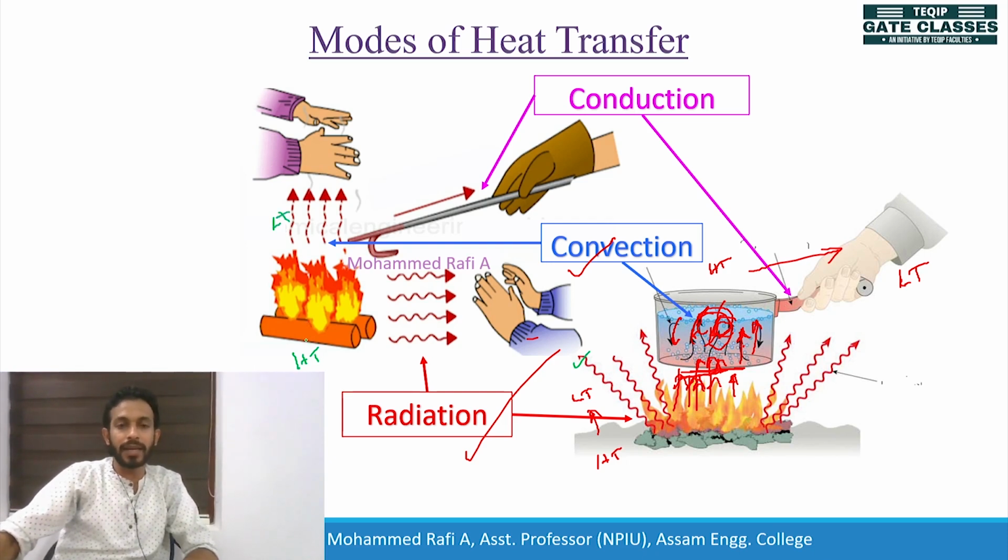Like I said, there will be heat transfer from high temperature to lower temperature. How will this happen? It will be either radiation or convection, because electromagnetic waves are emitted from that high temperature body, and thereby the heating takes place. That is radiation. And there will also be some bulk motion, because, just like in the water in the pan, whatever air comes in contact with this will absorb the heat energy and become light, so it will go up. At the same time, heavy air molecules will go down, so there will be a recirculation, a bulk motion, and that is called convection.